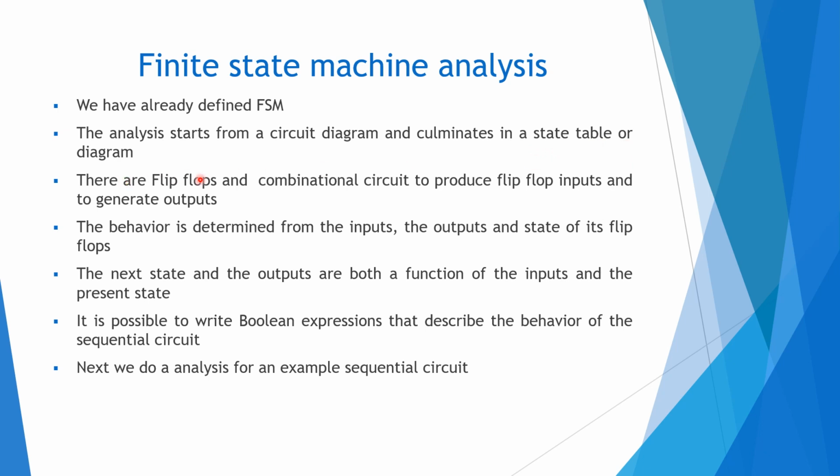In an analysis, we will be getting a circuit diagram, or logic diagram, that will be a synchronous sequential circuit, and we will be deriving a state table or state diagram in order to understand the working of the finite state machine. So there are flip-flops and a combination circuit to produce flip-flop inputs and generate outputs. The behavior is determined from inputs, outputs, and state of its flip-flops. The next state and outputs are both a function of the inputs and present state. Only according to Mealy and Moore, it varies.